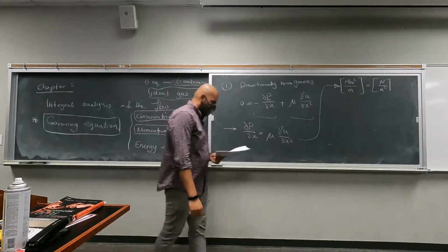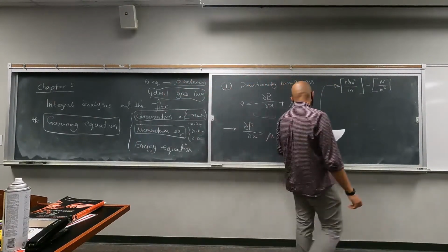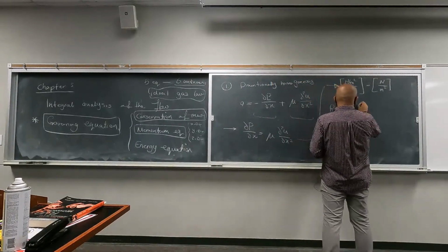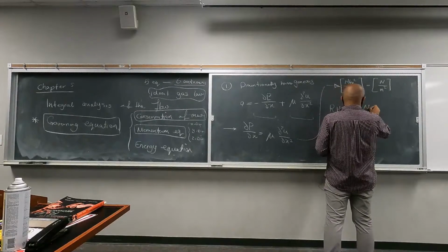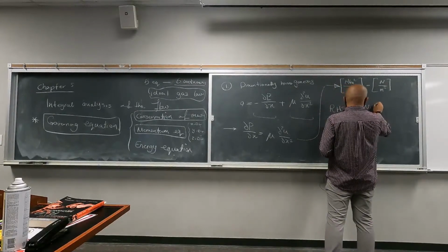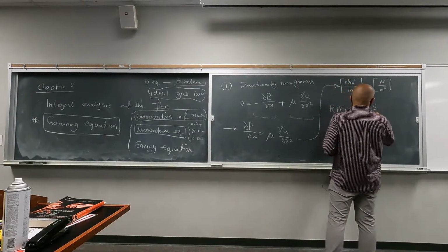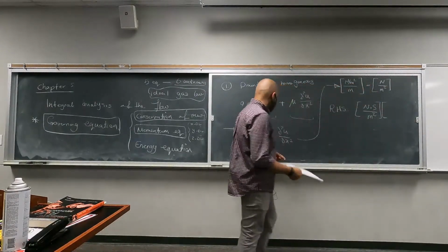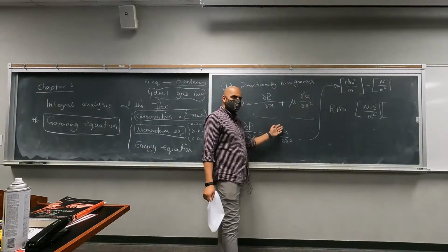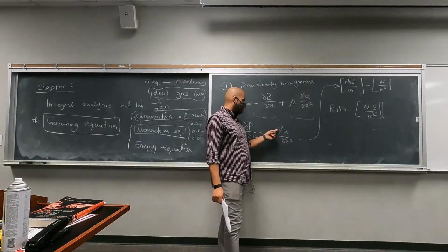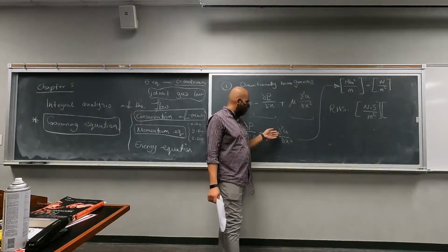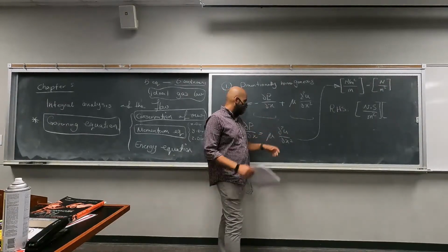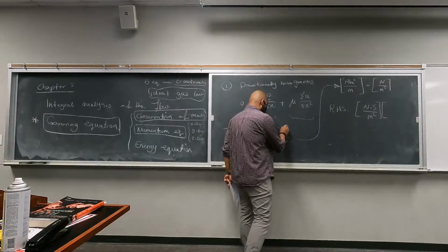And on the right-hand side, RHS, we have viscosity with the dimensions of newton seconds per meters squared, the dimension I gave you in class, right? And then we have the second derivative of velocity with respect to x squared. Partial operator, dimensionless, so it doesn't really matter that it says partial squared. What is the dimension of velocity?